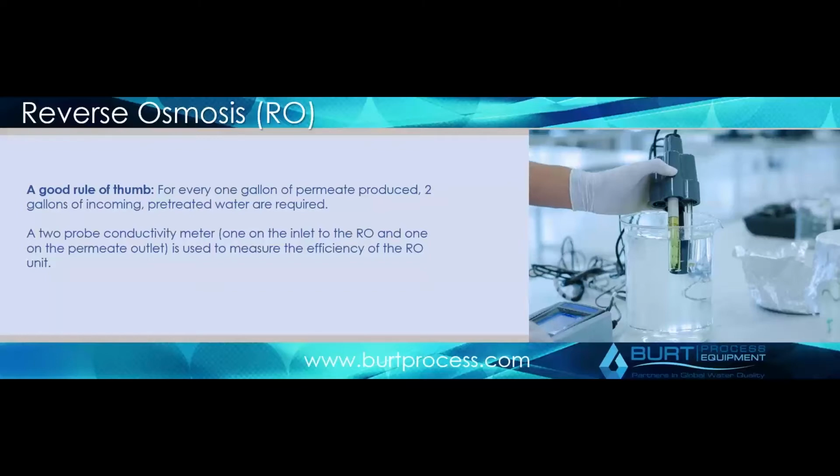Great. So that's a very significant consideration. Thank you. One of the good rules of thumb is obviously when you have an RO, as we were just talking about temperature, you do have this reject stream, and the generic rule of thumb is your reject stream is going to be somewhere between 50% for very unoptimized ROs up to about 25% reject rate for more well-designed ROs.